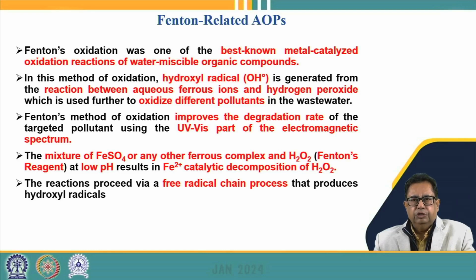So the Fenton's method of oxidation improves the degradation rate of the targeted pollutants through the UV visible part of the electromagnetic spectrum also. So if we have a combination of Fenton's as well as UV visible electromagnetic spectrum irradiated on such a wastewater, then it can result in the enhancement of the degradation rate. The mixture of ferrous sulfate and or other ferrous complex, when it is combined with H2O2, leads to the formation of a reagent which is called Fenton's reagent.